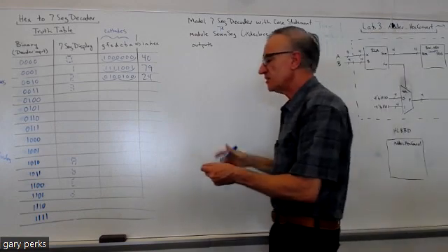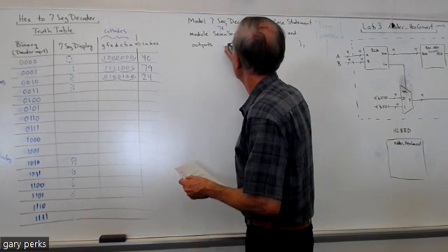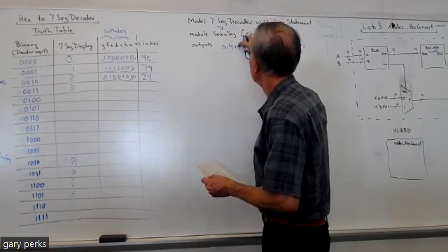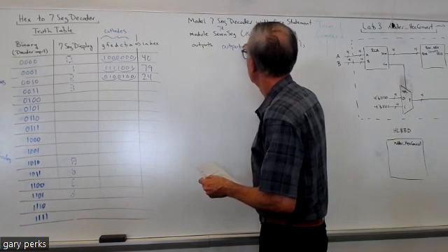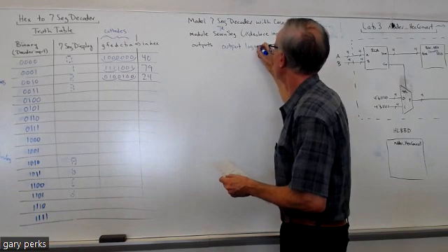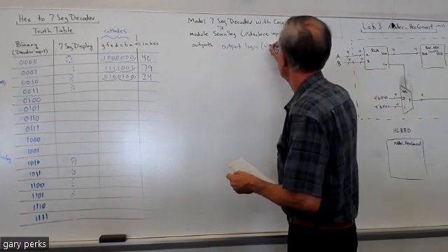So because of that, when we define output seg, we're going to have to do output logic, and then seg is 7 bits, so it's going to be 6 to 0.